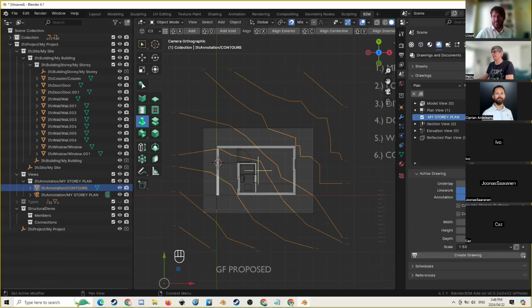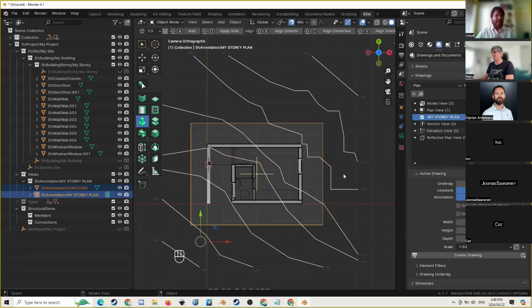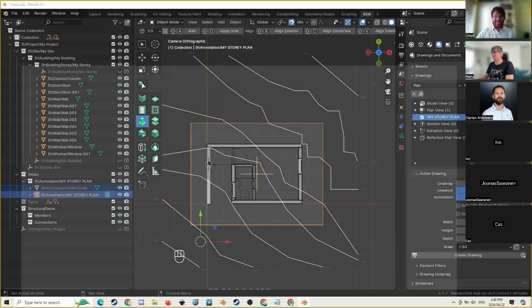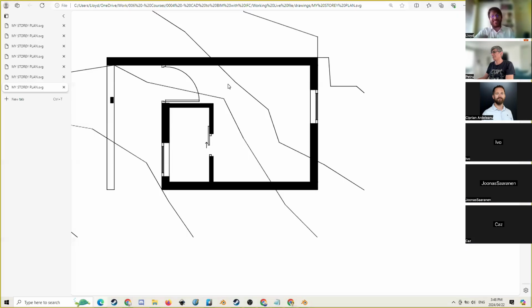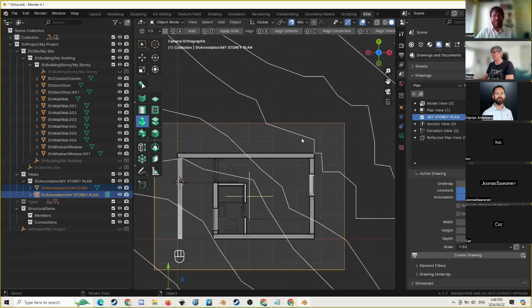And then I'm going to go back here, and I'm just going to say activate drawing. So you can see now the contours have turned white, and that is our 5-step process for assigning a single DXF layer as an IFC type. And at the moment, if I say activate and create drawing, it's just a solid line. So even to add that additional information is another layer that you need to do inside of Blender BIM.